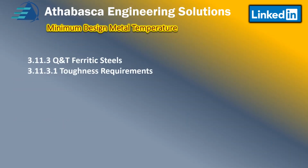Quenched and tempered ferritic steels have their own specific requirements in the section. The way Section 311 is laid out, there's one section for alloyed steel, another section for ferritic steels, and so on in different classes. And of course there are some overlapping requirements in 311.1. So let's talk about the toughness requirements.